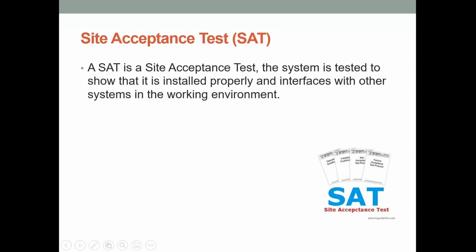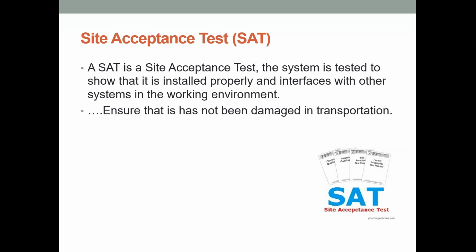The SAT, the site acceptance test. So in a site acceptance test, the system is tested to show that it's installed properly and that it interfaces with other systems in the working environment. So it makes sure that it's not been damaged in transportation as well.